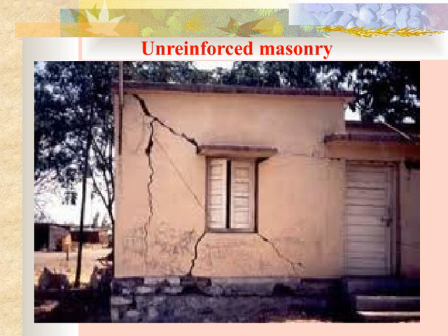This is a critical point to understand because, as we look at building safety and retrofitting strategies, unreinforced masonry buildings often require special attention. Retrofitting can involve adding reinforcement or other techniques to improve their seismic resilience. Overall, recognizing the limitations of URM is essential when assessing the seismic vulnerability of existing structures and planning for safer, more resilient buildings in the future.